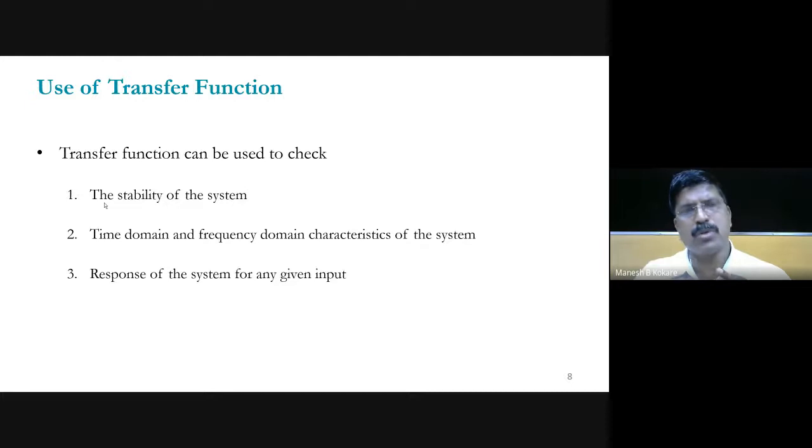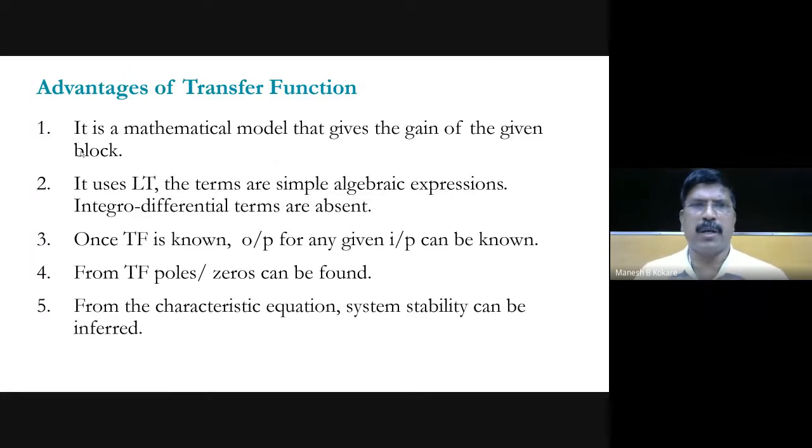And the third use of this transfer function is that we can determine the response of the system for a given input. So whether that input is a step input, or parabolic input, or ramp input, or sinusoidal input, or this impulse input, any kind of input if you have, we can determine the output of that system if you know the transfer function, right? So these are the three uses of the transfer function.